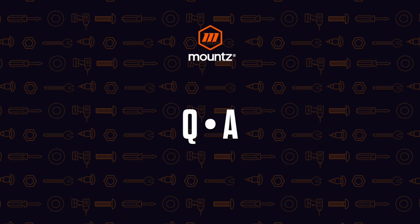So let's say you've got a Phillips bit, a Phillips 0 or 00, and then you need to move to do an assembly with a Phillips number 1 or something like that. Something that could work but doesn't work the best and may cause some galling issues or some stripping or threading or errors on the fastener. And so we can put the fasteners within a bit socket tray.